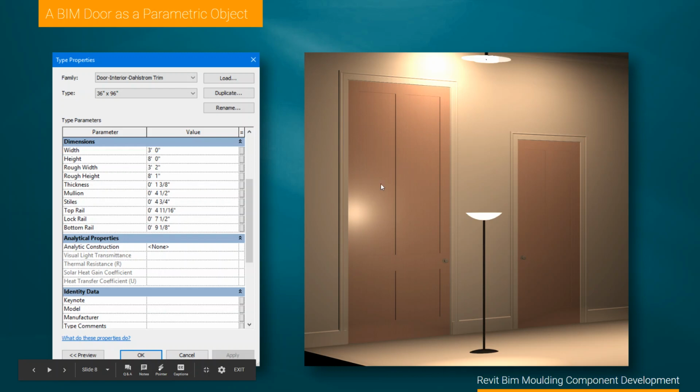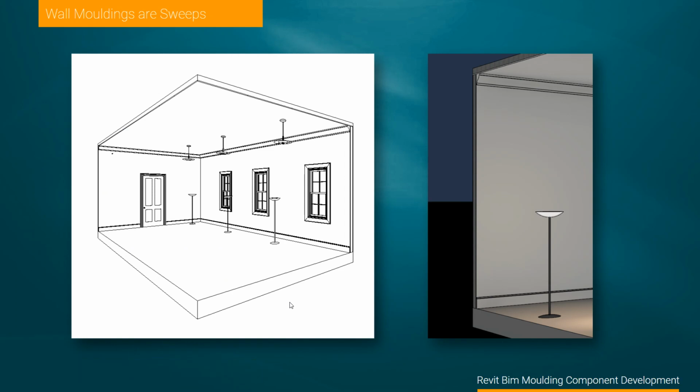So the doorknob is parametrically linked to the ground plane to have a certain fixed distance to it. So no matter what the change of the height of the door, it will always have the doorknob at the right location. And likewise with the width of the panels, the board that would sit between the panels would always stay the same so that it's accurately scaled up without having to reconstruct building elements. And we should keep that in mind when we build BIM components, that they behave the same way.